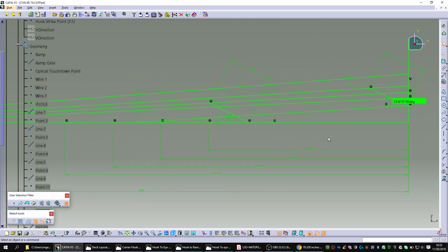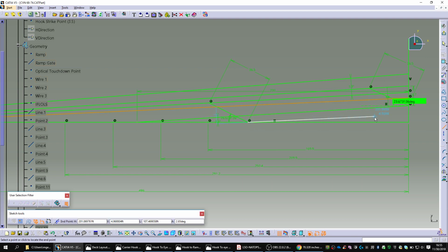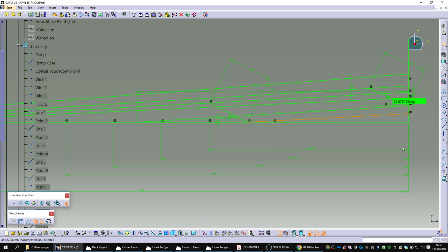Let's see if this passes another constraint though. Just because you get a lower amber meatball, I'm concerned about it meeting the 10-foot deck height limitation. Because I know this is the lower amber glide path, I know the hook has to travel along that same path. All right. Let's see if I can pick the correct parallelism here. Not that one. Hey, do you see it snap there? There we go. I could apply it manually, but if I get it in the first take, that's good.